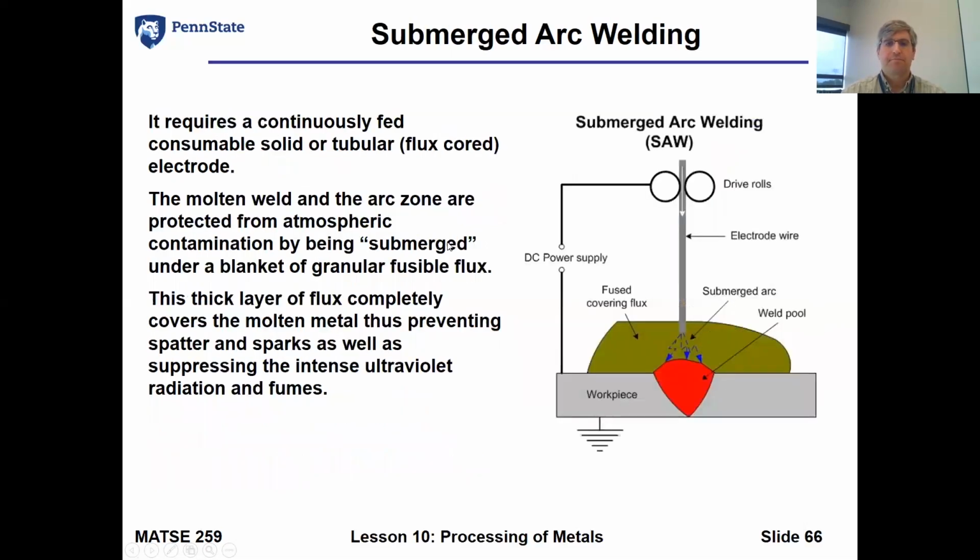that flux is. Submerged arc welding is, just as the name sounds, a continuously fed process. There's no shielding here because they literally cover the electrodes. So the electrode is buried in what's called a flux, which is that slag. It creates that slag. Now submerged arc welding is typically used for really deep penetration welds. It's a very high efficiency process, where you feed a rather thick electrode wire.